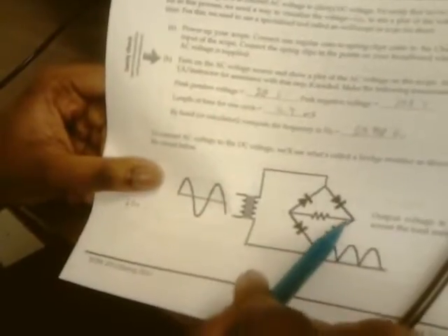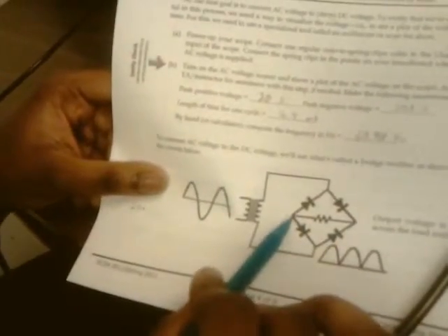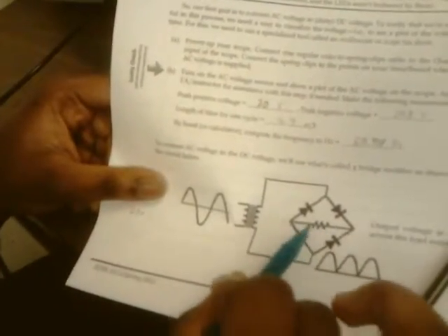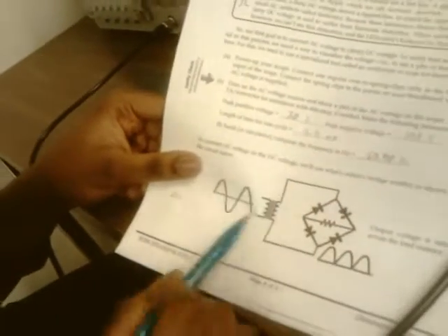It's going to pass through 4 diodes like this. The current enters through here and goes this way. Then it passes through this resistance here, and comes this way and comes down. This is going to remove the negative part of it to make it a direct current, giving us this graph. And when it enters here, it can also go this way. So that is the main function of a rectifier. It rectifies an AC voltage to a DC voltage.